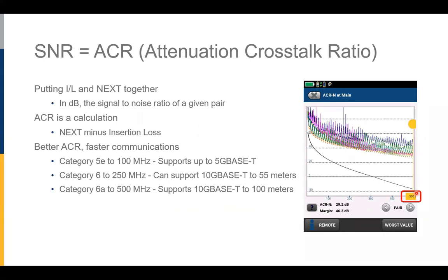That is going to exceed 1 gigabit in the air from your cell phone up to the wireless access point. So if you have multiple radios in a wireless access point, you could be exceeding 1 gigabit per second. And that's today. In the future, we're going to have greater speed. And that's why you're going to find the recommendation that for wireless access points, we install category 6A cable so that we have the additional bandwidth available to support those new wireless access points in the future.